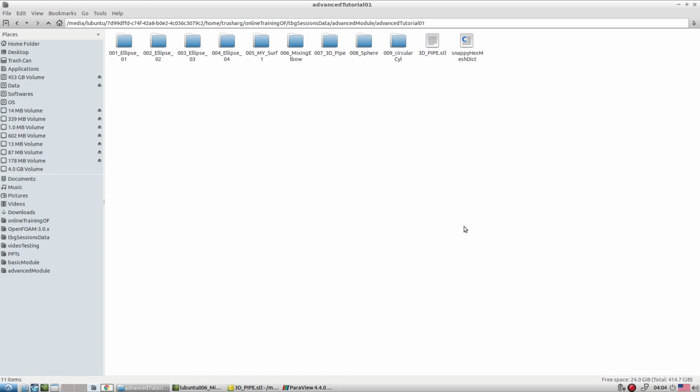So till now we explored the three-dimensional internal as well as external mesh. But let's say we want to construct the mesh for two-dimensional calculations. By default, snappyHexMesh gives us the three-dimensional mesh only, but there is a way you can construct the two-dimensional mesh as well.